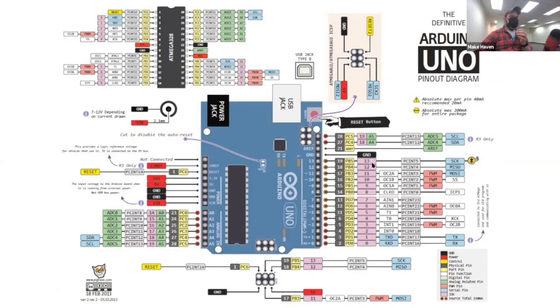So this is what they're labeled in the development environment. If you say, I want pin 3 to blink an LED, you say pin 3, and it's referring to this spot on the actual board. But there's a bunch of other things going on. It has this particular code for its existence deeper down in the software. It can pulse width modulate. You can describe it as being a PC int and do all sorts of stuff. There's tons of different weird options that you can do.